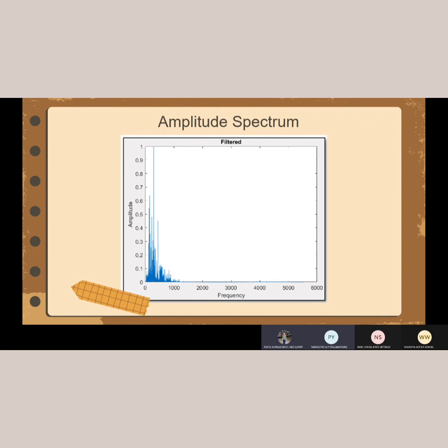In conclusion, the zero and pole graph is generated to check its stability, and the audio is tested again to check its smoothness after the filtering process. We applied the IIR filter in digital filtering because the IIR filter requires a lower filter order, thus less complexity. And that is all from us.